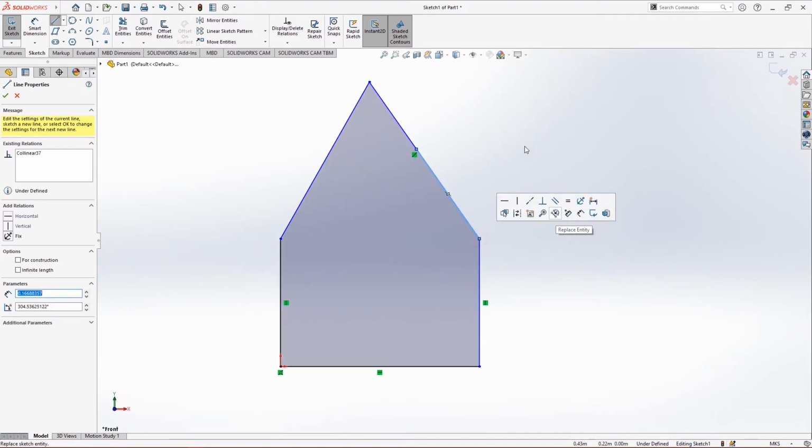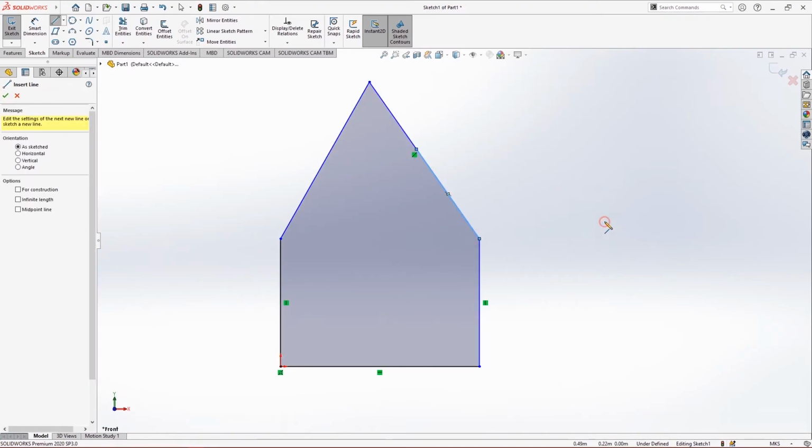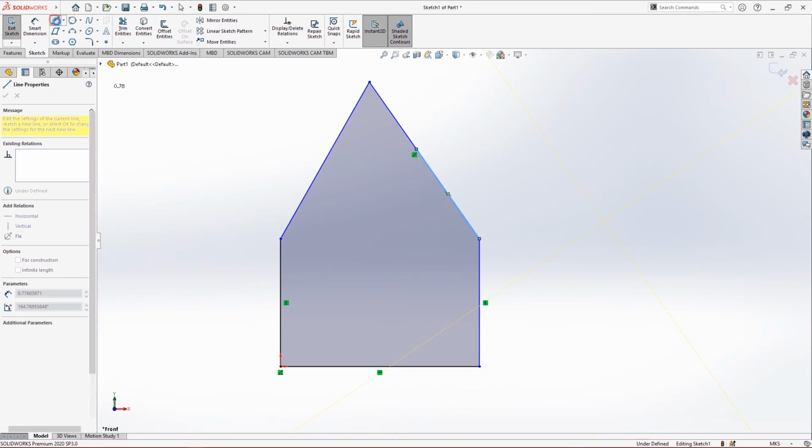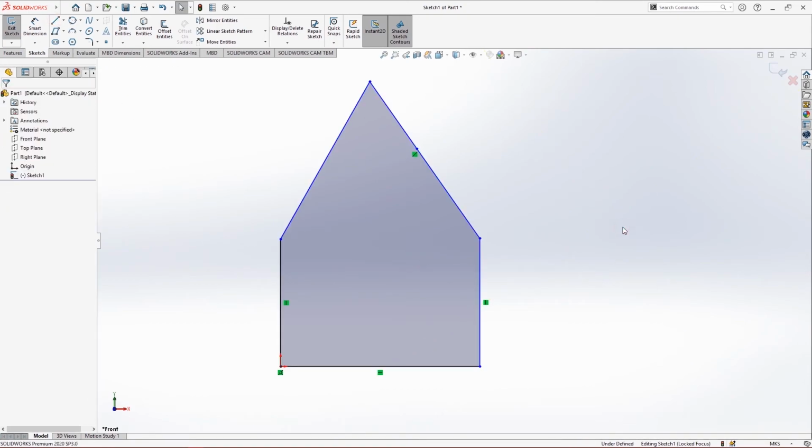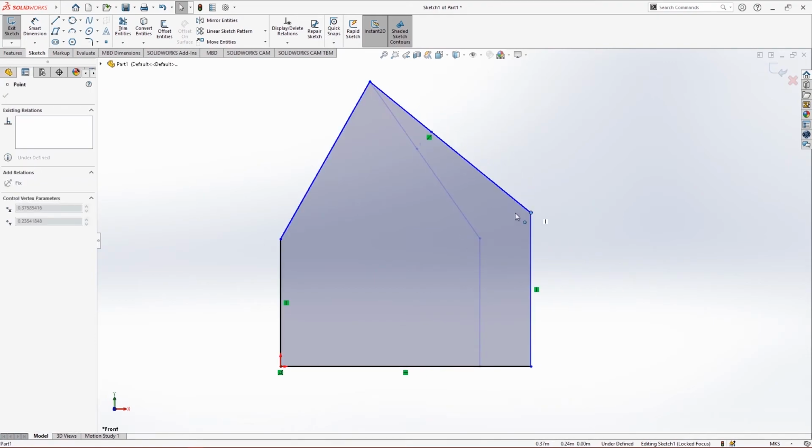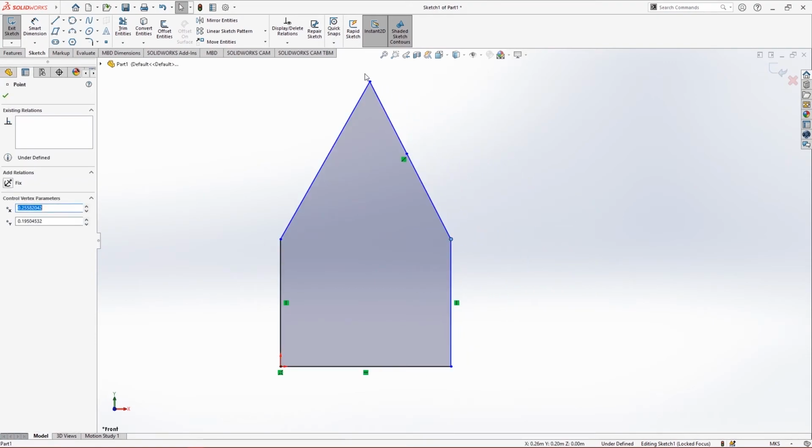Okay, so you can see we have a closed shape now, but still when you look here, these two are in black and these are in blue. So what happens there, these two lines are actually fixed about the origin, but this is not fixed, so I can still change these values. So we'll have to define the sketch so that it remains the same.